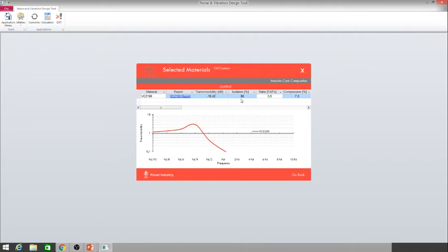Like I said in the beginning, when we increase the thickness, we are increasing the insulation. And we defined 40 millimeters as the limit we can supply in a higher thickness, but the gain that we can obtain by using a higher thickness will not correspond to the gain in terms of insulation. So 40 millimeters will be the best performance thickness that we suggest.